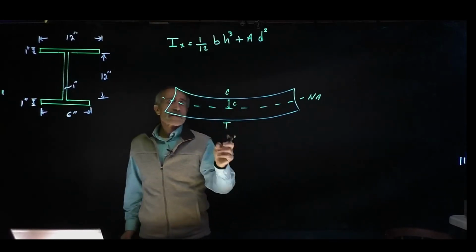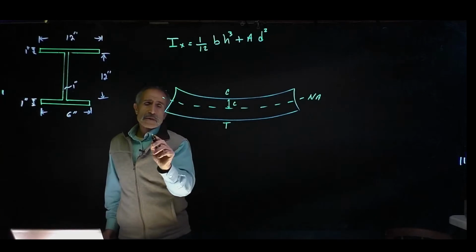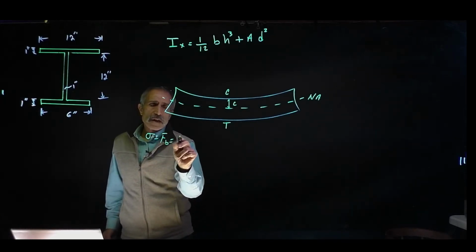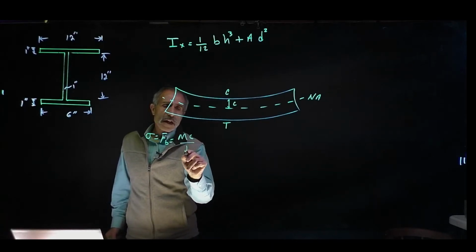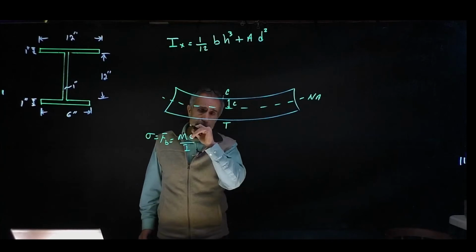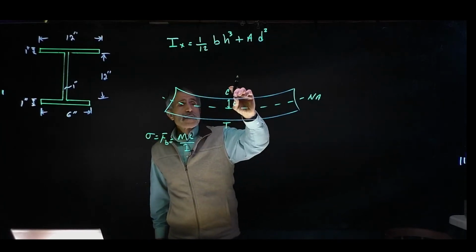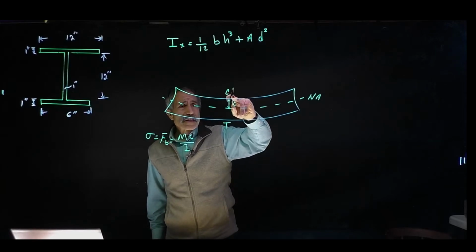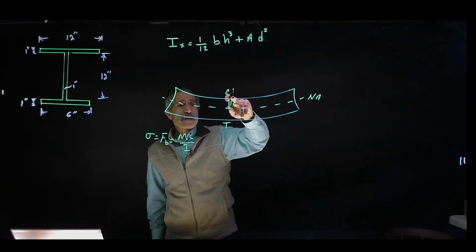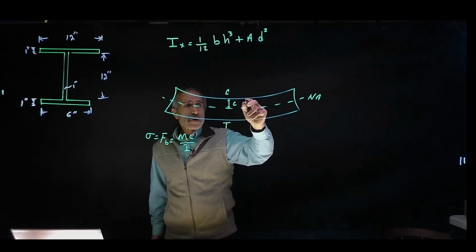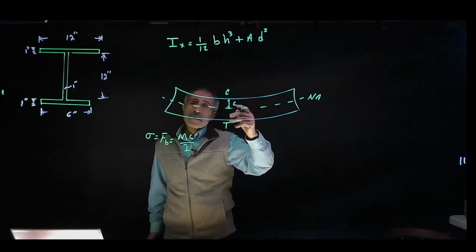And then you have a stress. Your bending stress or flexural stress, sometimes it's sigma, sometimes they say f_b. That's basically Mc over I, where M is the bending moment. You will learn later on what bending moment is. On top of the beam, where you put a weight on it, the maximum compression is right there, and the maximum tension is at the bottom. As you get closer to the neutral axis, the stress is zero.